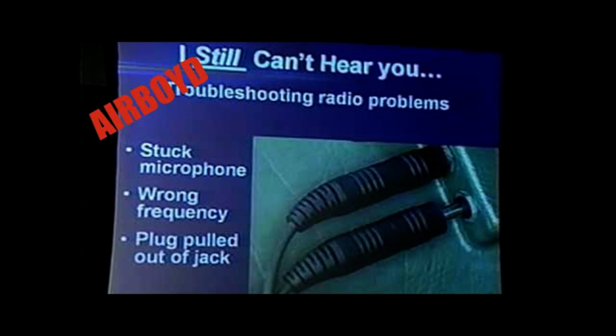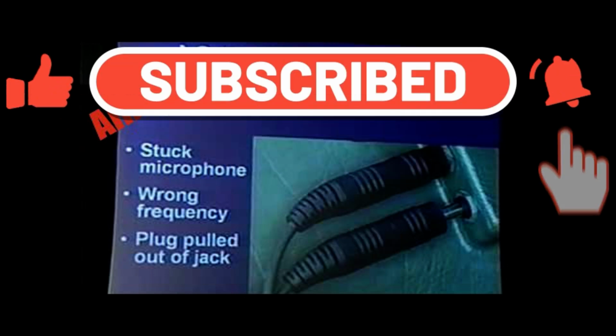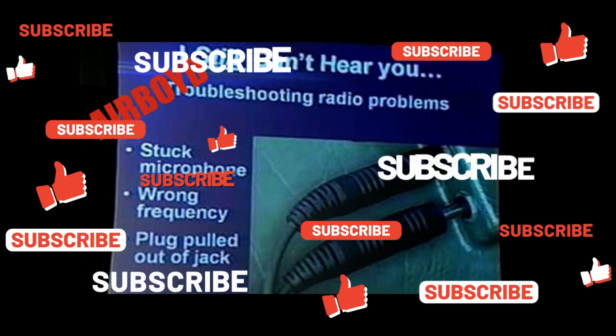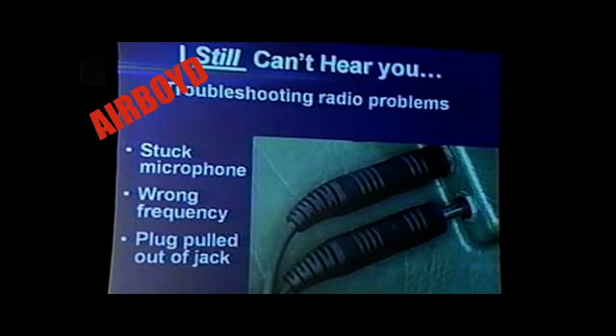It is important that the pilot wait at least 1 minute before deciding that the ARTCC has actually experienced a radio frequency failure. When such an outage does occur, the pilot should, if workload and equipment capability permit, maintain a listening watch on the affected frequency while attempting to comply with the following recommended communications procedures. 1. If two-way communications cannot be established with the ARTCC after changing frequencies, a pilot should attempt to recontact the transferring controller for the assignment of an alternative frequency or other instructions.